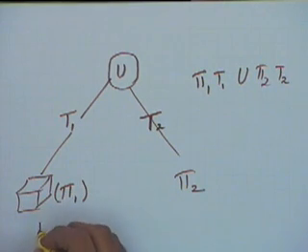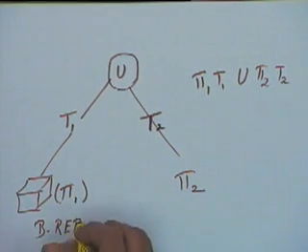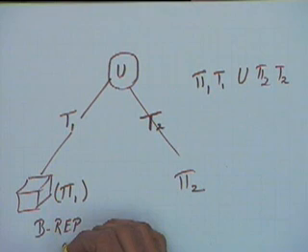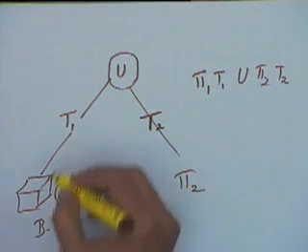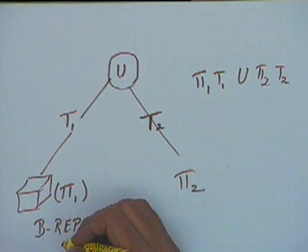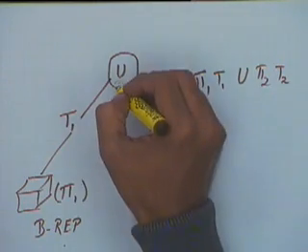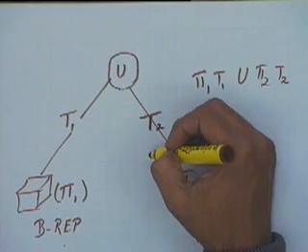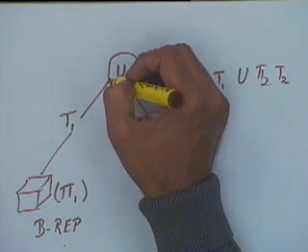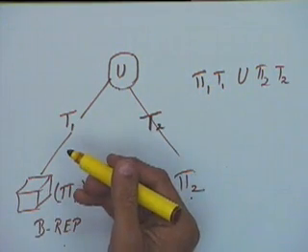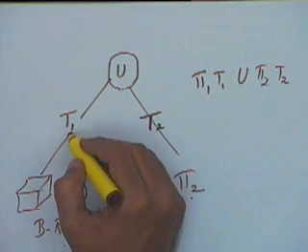Let us say this solid is represented using either B-rep or some graph based representation. Okay, this transformation is not going to alter this representation. The transformations are not going to alter the topology of this object, only the union operation is going to alter the topology. All Boolean operations can alter the interaction between the different surfaces. New surfaces can be generated, new edges can be generated, and new vertices can be generated by a Boolean operation. But that cannot happen by a transformation.